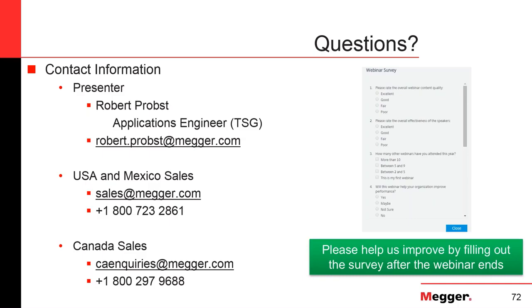Yeah, I know from field experience that certain utilities are testing important circuits every year, or even the manufacturer requires it, for special applications, or it's DC, so primary injection also applies to DC. And sometimes these breakers are tested every year. Sometimes the time is extended, as John said. But that is to be decided by the user. You have to come up as a user with the test procedure, and you have to validate and pretty much defend that procedure, and you have to justify it.